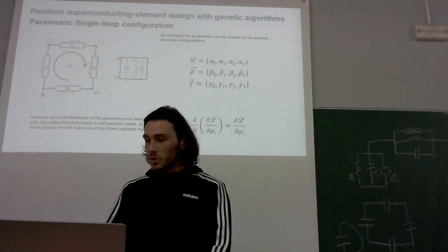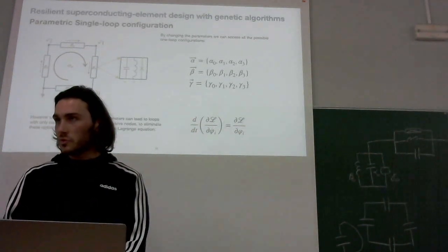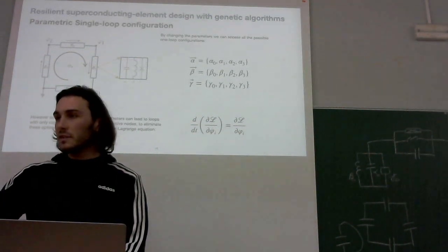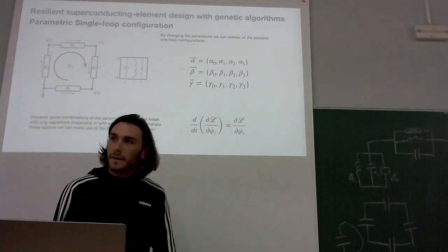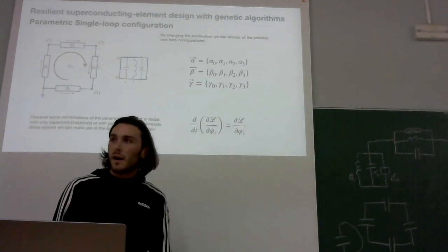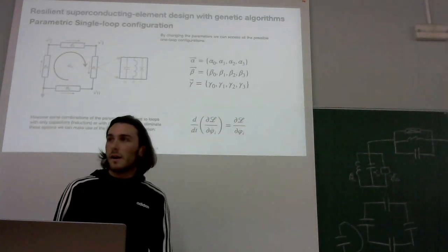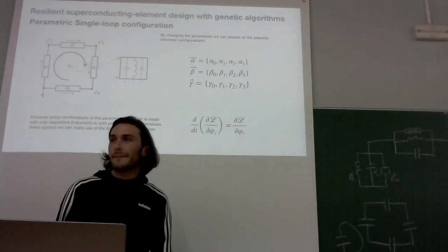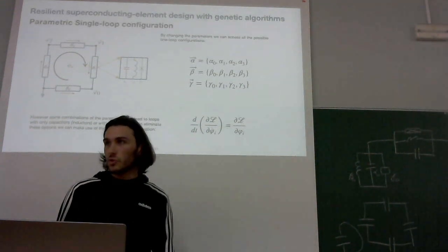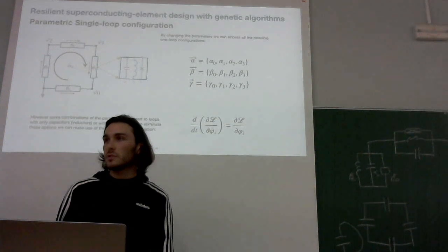Yeah, so we want a circuit with these spectrum characteristics, with this energy difference between levels, and with these transition rules. But what is the minimum size that you need? A physical qubit will have to be an anharmonic solution. What is the minimum size of the loop that you need? 2 elements. To have a qubit, you only need the capacitor and the inductor.